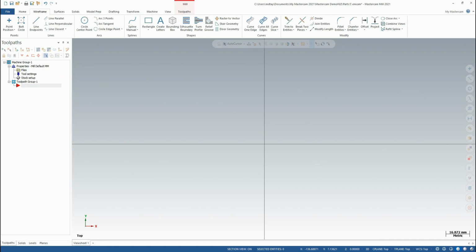Finally, what about our finishing technique? Am I going to need separate toolpaths for finishing the features of this part? How tight are my tolerances that I'm working with? Can I get away with just roughing cuts? Or do I need multiple finish cuts? Do I need spring passes? All of these things are things you need to take into account.